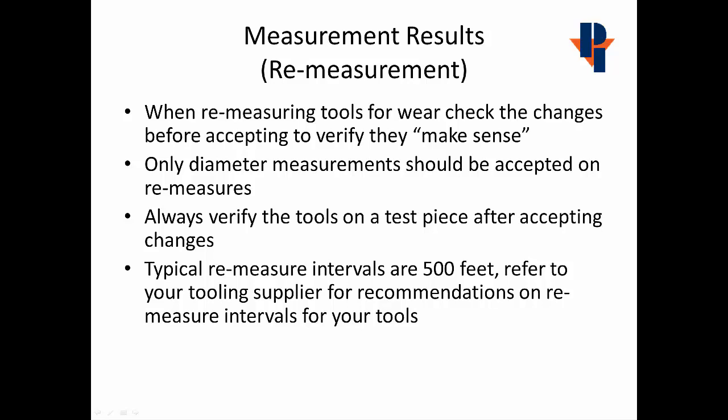Remeasurement. When remeasuring tools for wear, check the changes before accepting that they make sense. Only diameter measurements should be accepted on remeasures. And after measuring any tool, always verify the tools on a test piece after accepting the changes. Typical remeasurement intervals are 500 feet. Refer to your tooling supplier for recommendation on remeasure intervals for your tools.